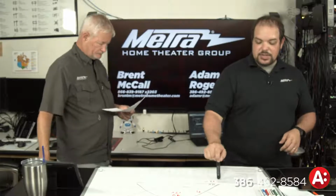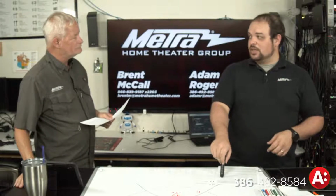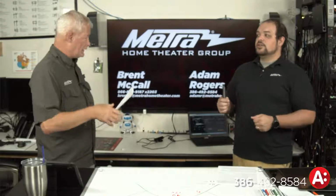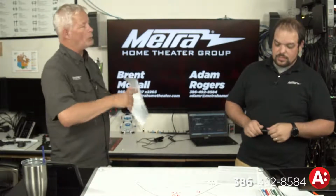Now, I will say that this specification here is for PoE and PoE+. This is not the new PoE++, the 4P PoE. So this is a little different. For the new stuff, because I would assume it's using all 4 pairs, there's an entirely different interrogation process. Yes. It's probably much more complex. Correct. Because it's not just voltage, and now it has to determine how to parse out the data.